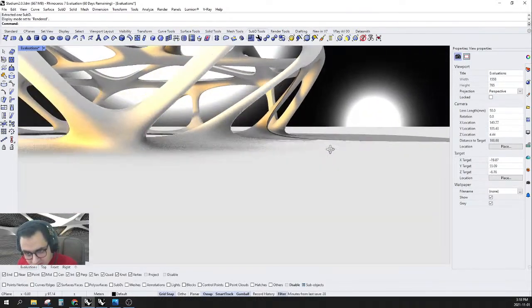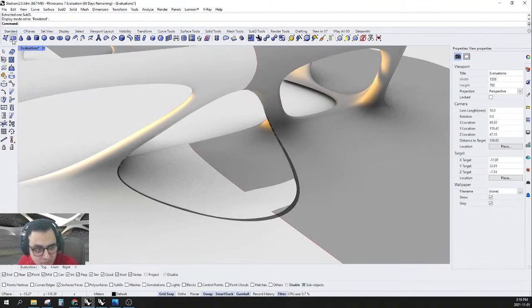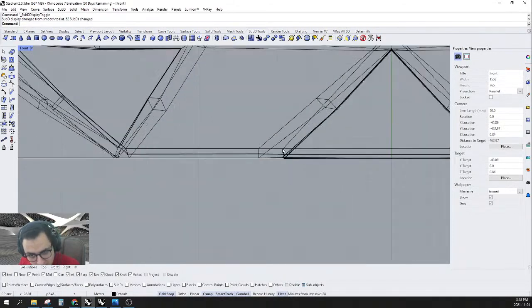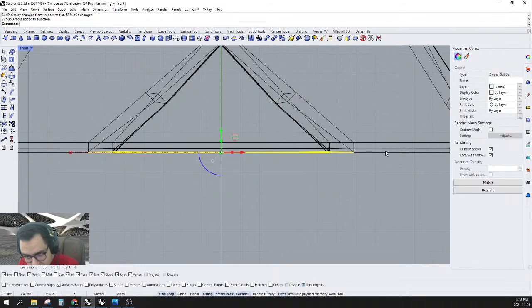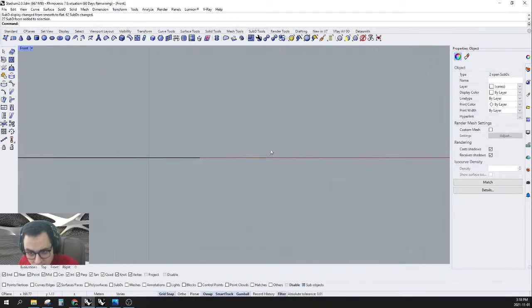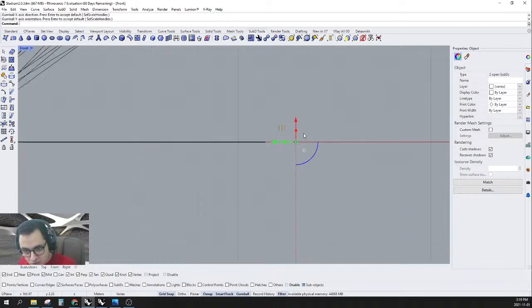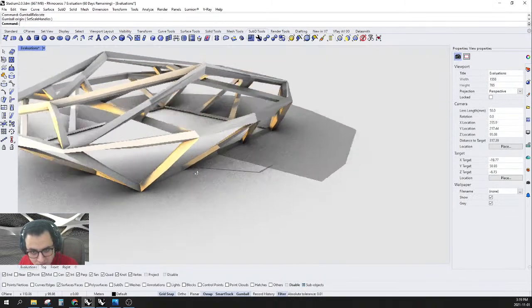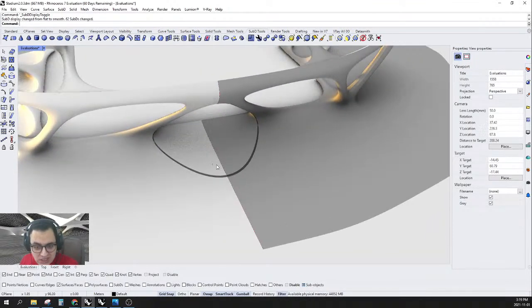Now this is not perfect because somehow it's not at the 0 level, so we need to fix it. Or is it on the 0? Let's go to the front. Yeah, because of the bevel, there's something not quite right in here. So simply select all of these and go to here somewhere away, and go to Gumbo relocate again, and from here to here or wherever, and simply select the red one and 0. So now it's perfectly level. So if I go to here and go to here, you can see that it's perfectly level with the ground. So that's important.